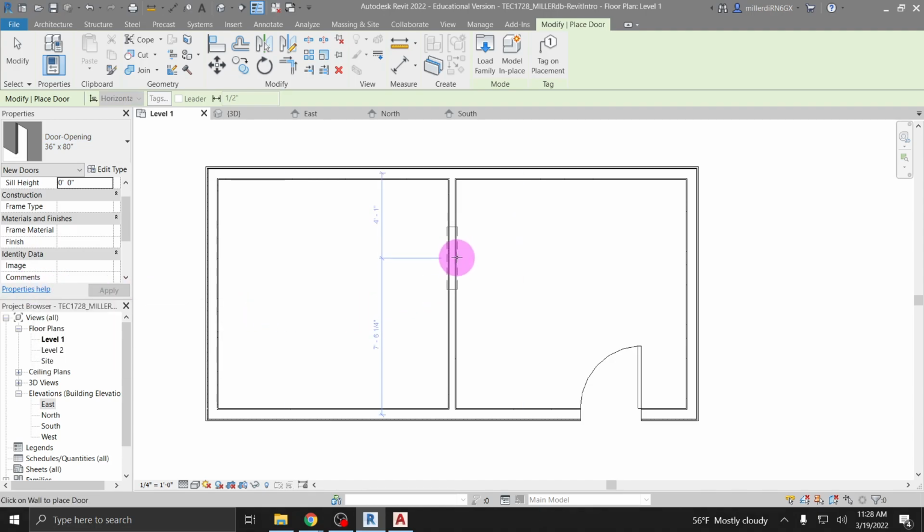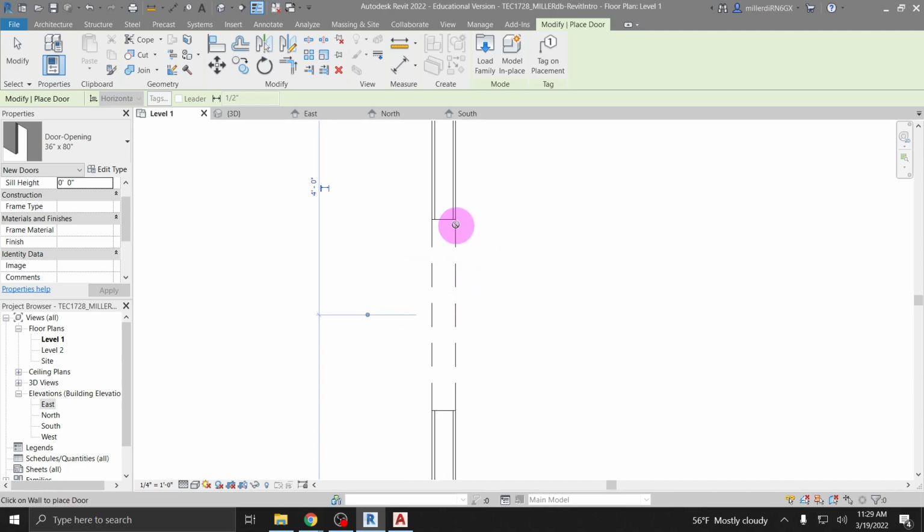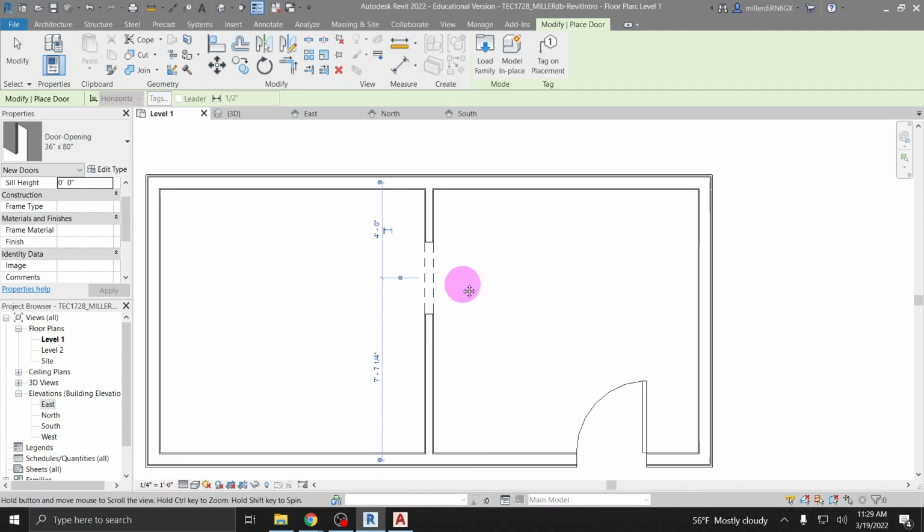And then I'm just going to click to place it. I always just kind of round about where I want things, and then afterwards I'll go put in the details. And since it knows this is a cased opening and not a door, it puts in the hidden lines for us automatically. It fixes all of these little details and trims everything for us automatically, just like it did here with this door too. It put the symbol in. So Revit's taking care of a lot of that architectural symbol stuff for us since it knows what it's doing.